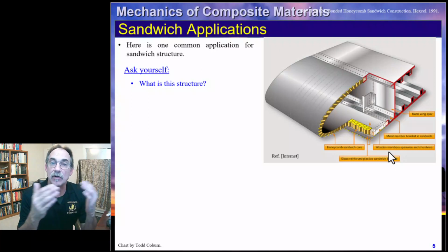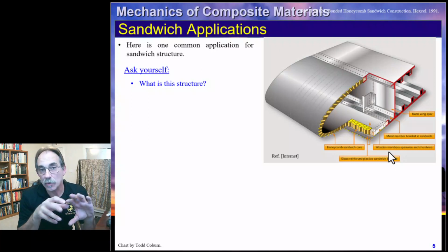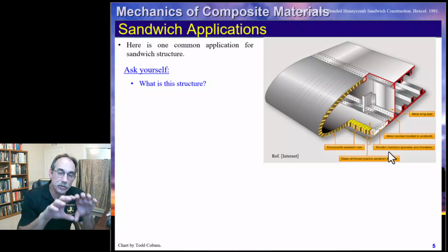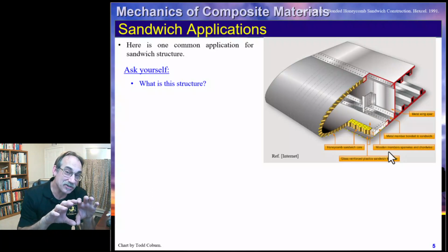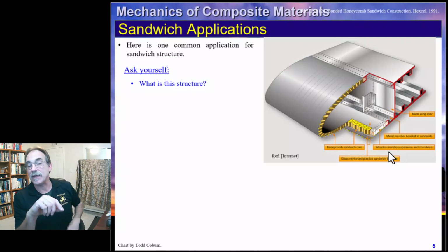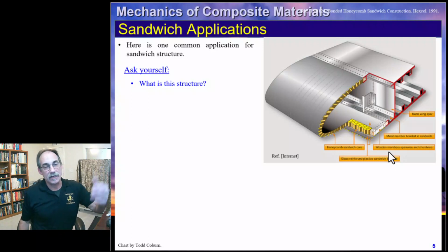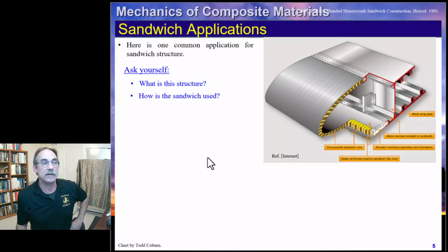You can see looks like solid material stringers back there in the background. We can see face sheets carrying the load, but then on the leading edge, where you get a lot of dynamic pressure applied, in order to keep that shape, you're going to get pretty good resistance just from the curvature of that structure. But then by making that a honeycomb or a sandwich kind of structure, it will resist even more localized bending than it otherwise would. So if you get a bird strike or something like that, that's going to be more resilient. You can see that that's providing, in this particular case, more localized bending capability that's continuous across that leading edge.